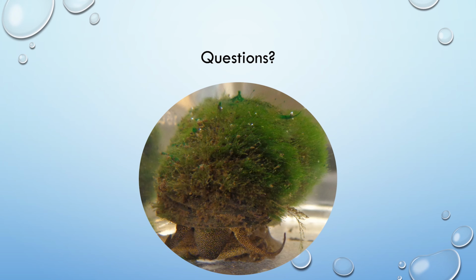All right, we have another question here. In a 5-pond system, which pond should you attack sludge? If you use it in the first pond or 2, will that reduce sludge in the next 3 ponds? That might really depend on the situation you're dealing with. The closest thing I remember treating was a golf course that had a situation where there were 3 ponds in series, one into the other. And yes, when we saw the sludge build up in pond 2 and treated that one, we saw less sludge in pond 3 and also less algae blooms, which is mostly what they were concerned about. So it could be done.